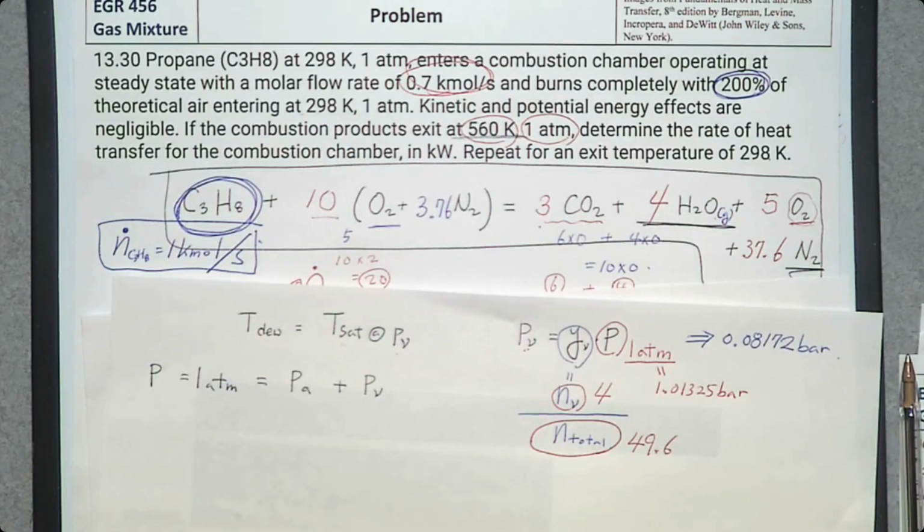Okay, now we have the vapor pressure. Let's determine the saturation pressure. How do you determine the saturation pressure when you have vapor pressure? Do you remember how to determine saturation pressure? That's what we did a long time ago when we studied Thermodynamics 1. You go to the saturation table for water, the pressure table, table A3.